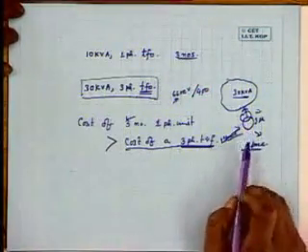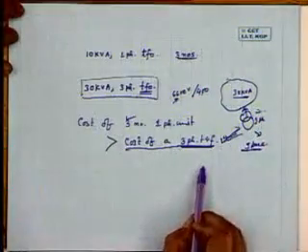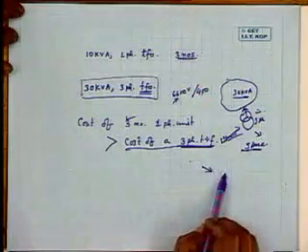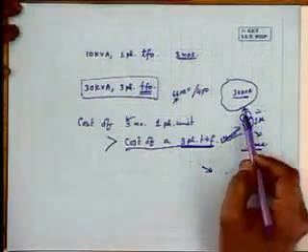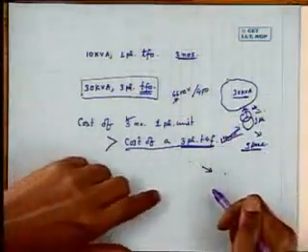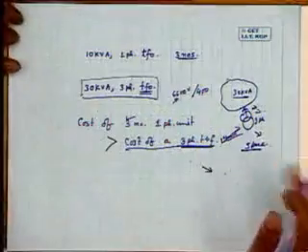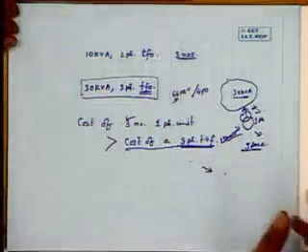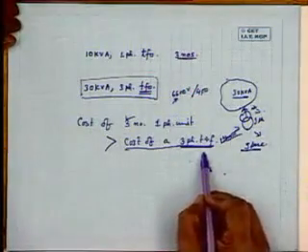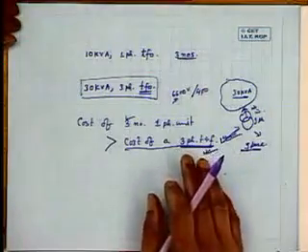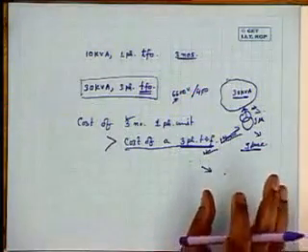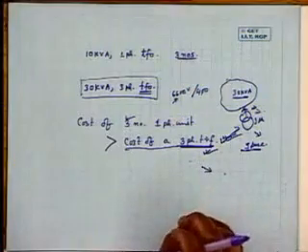Now the moment you go for a three phase transformer, you must keep that in mind, and you have to buy also a spare transformer, not a single three phase transformer. A spare transformer you have to buy. And once this transformer develops a fault, you take it out, put this one into service, and maintain the other transformer in the meantime, and that one becomes the spare for any eventual situation. So in effect you have to invest for two transformers if you really want to mean business with your customers. There is no other way out.